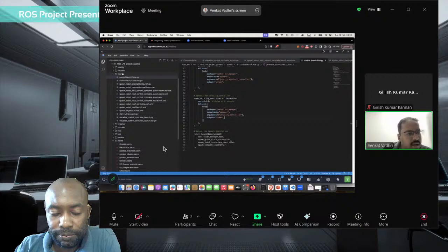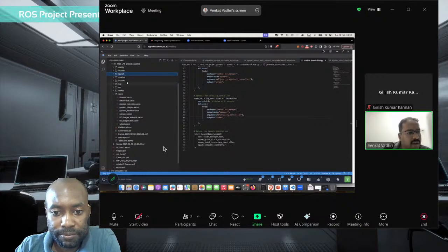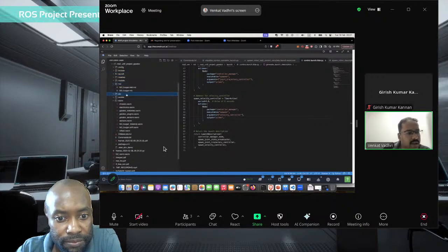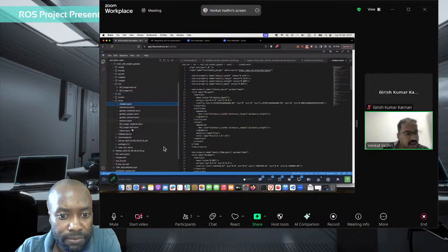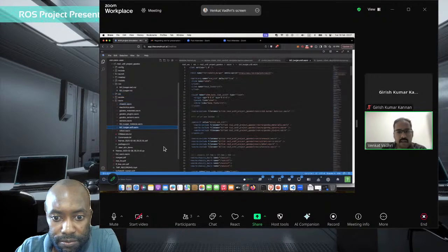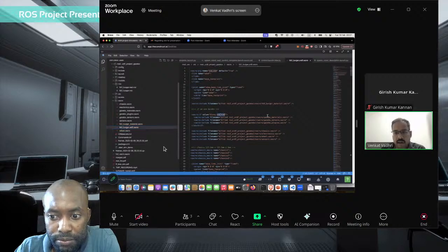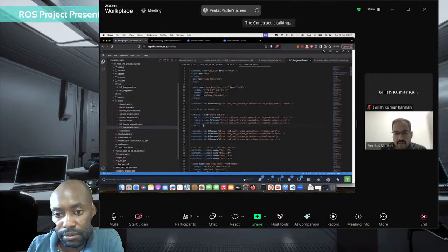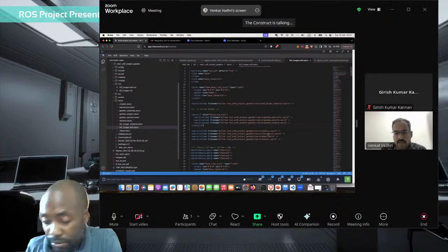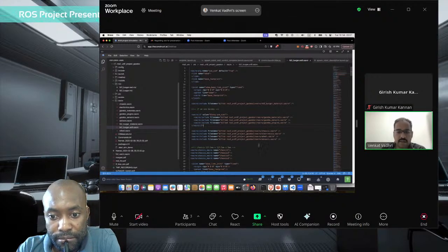Right. And if you see the Xacro related files, inside the Xacro files we actually include... this is the main Xacro file. In the main Xacro file, we have conditional loading of Gazebo materials and Gazebo plugins. If we are only using the simulator, for a real robot, this wouldn't be there. And after that, we load independent files, which are chassis, electronics, wheels, sensors, etc.